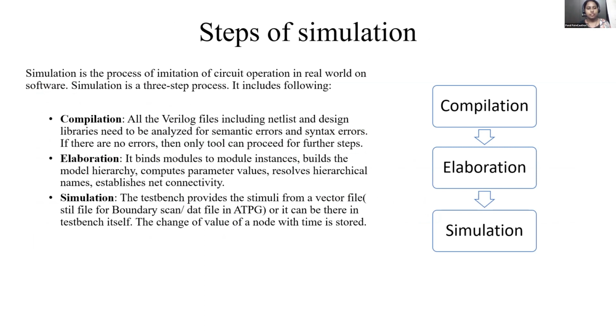Now the actual steps that we run to execute a simulation are: first we compile the code, whatever our test bench is, whatever our design is; we will just compile and look for syntax errors or anything in the compilation. If compilation passes, then we elaborate.